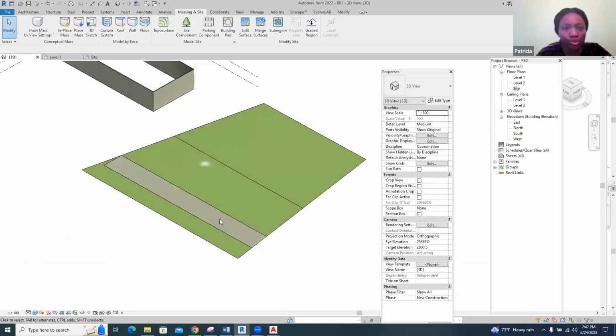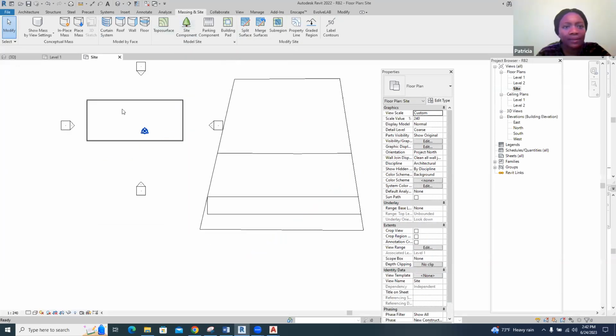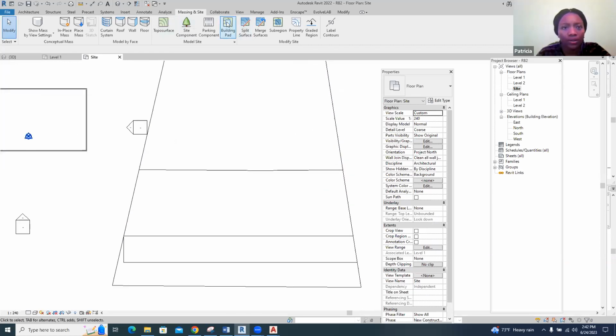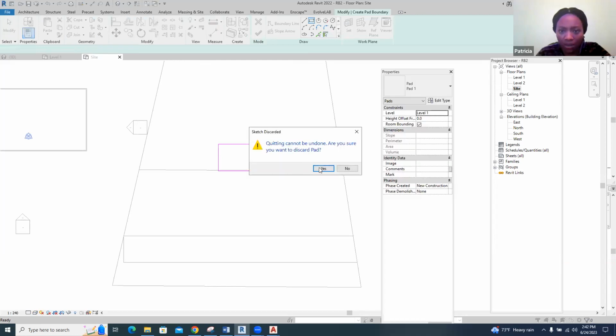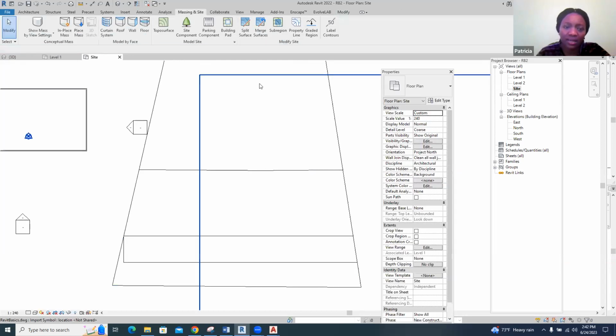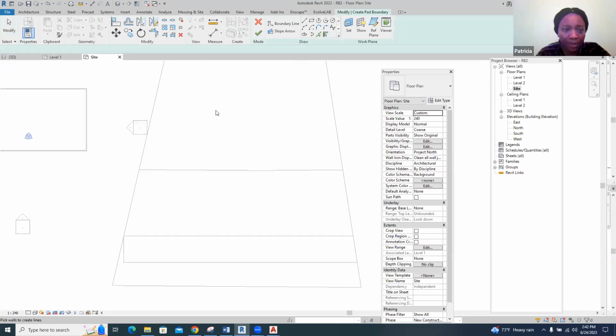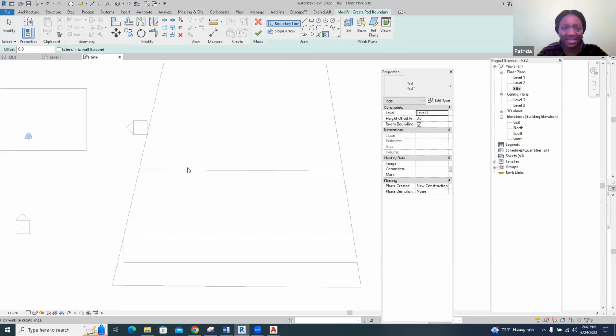And then we want to put the building pad on this site. So go back to site level and then get the building pad, select the box. While you're moving, is another thing, so I'm canceling this. I want to discard it. Yes, so if you press the X, that goes. If I select the building pad, as I'm moving, it will be aligning, select the box. So it will be aligning to the things that are already on the site.